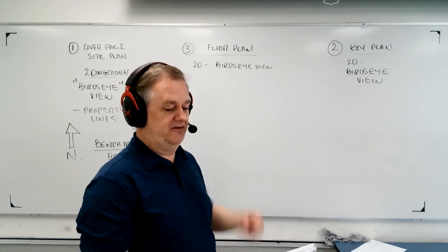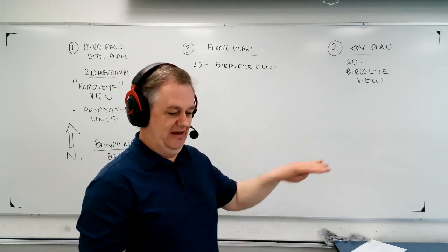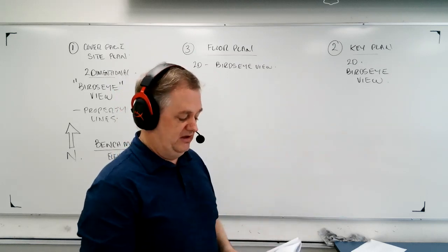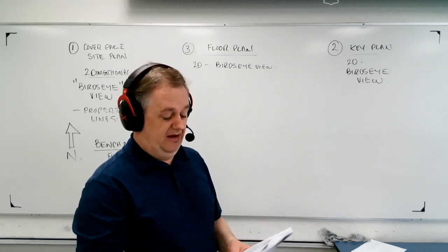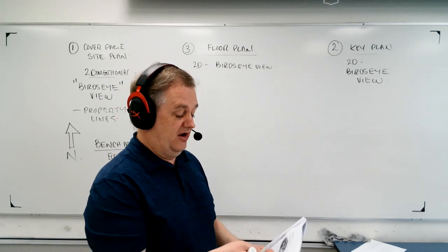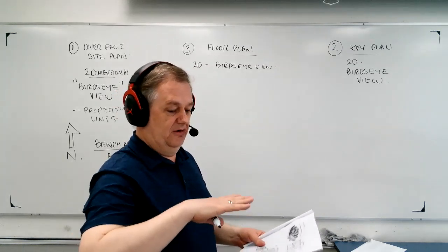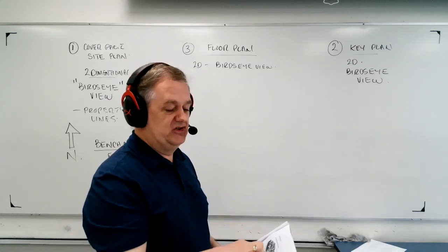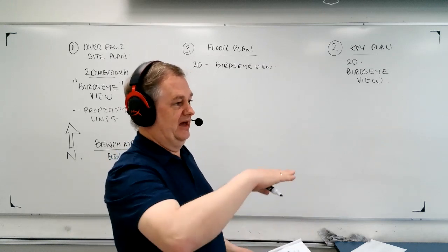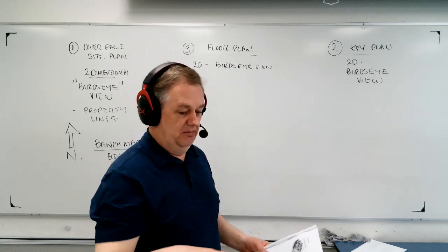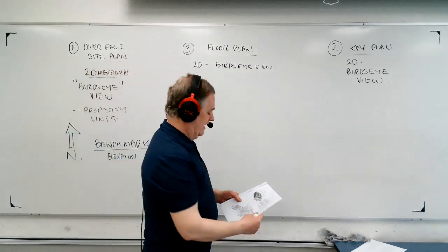So in other words, the floor ceiling height, you cut it through the middle, just like a slice, and you take the top off, and then you do a straight down bird's eye view shot of what you see. And that's why you'll actually see on that drawing anything that is up to about 4 or 5 feet high, you'll see it shown. And that's why you'll see half of a stairway, because that's about the height that the stairs would get to by the time where you made that cut. So very, very interesting to understand that about the floor plan.